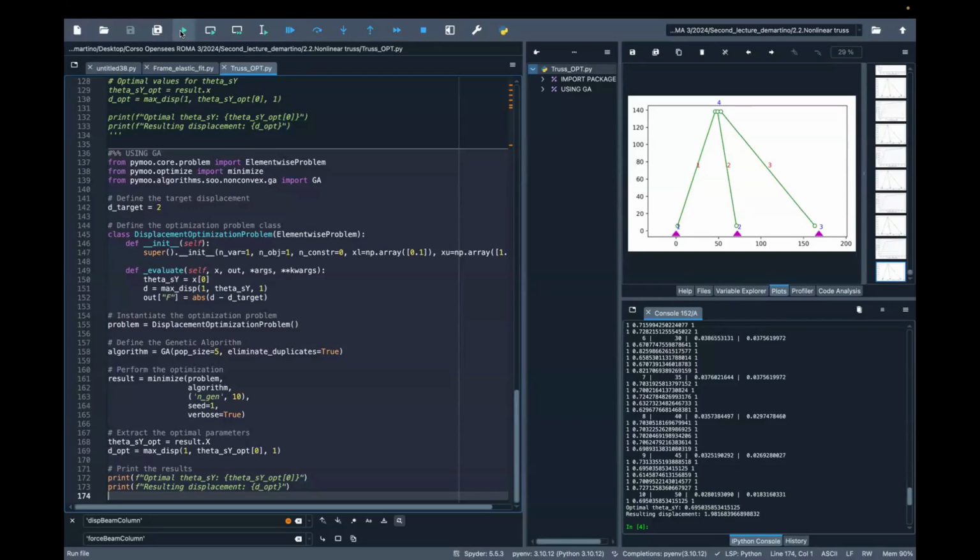This is a typical problem when you have experimental data, for instance, right? You have a model, you have experimental data, so you want to reproduce a certain response, you define your goal function, and you can tune the parameters in order to reproduce it. Please keep in mind, obviously, that a solution with a certain set of parameters is not necessarily the right solution. So sometimes this is called tuning parameters. You always have to think if the parameters make sense in a physical space.